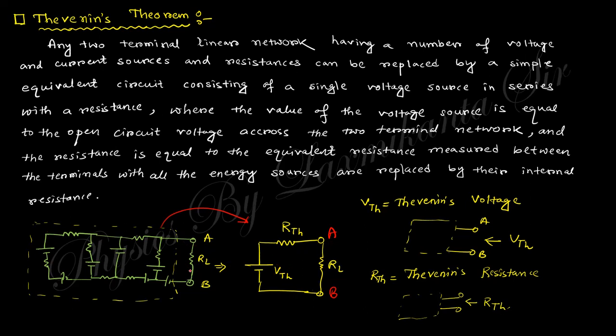VTH is the voltage you measure at this terminal using a multimeter or voltmeter, after removing the load resistance RL.